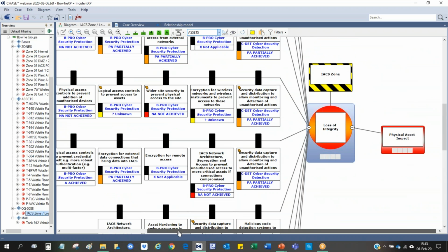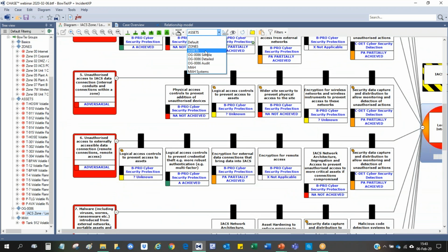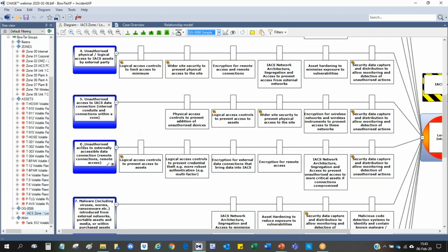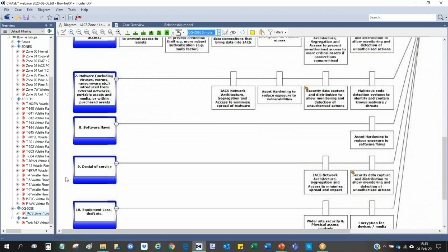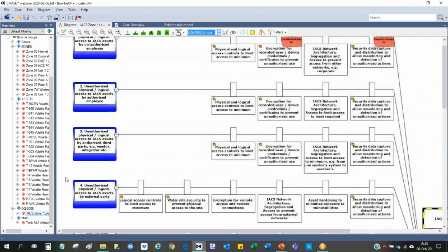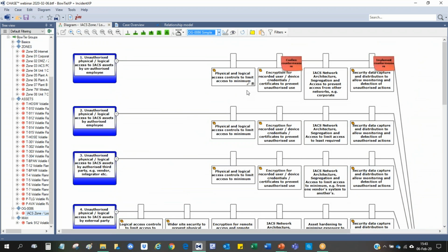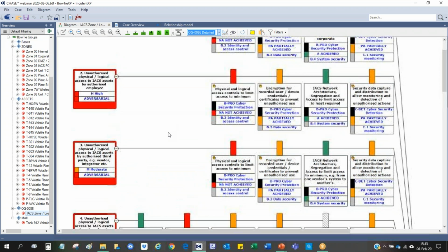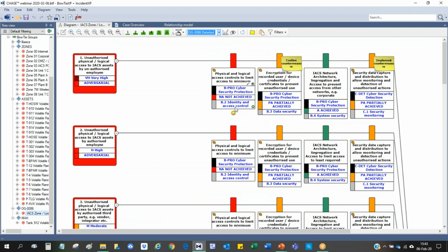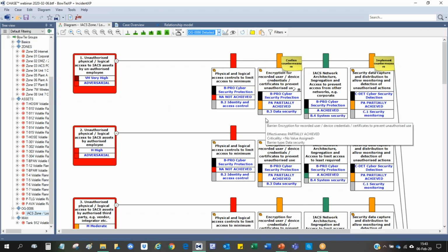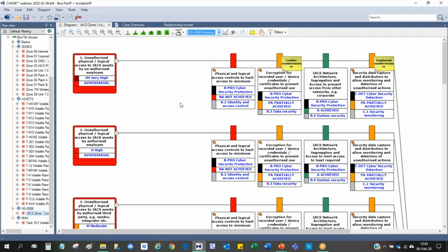Looking at this in more detail for the logical bow tie, here we've got our 11 familiar threats. We've got the expected or anticipated measures in place, and putting some more detail on it: what is the likelihood of the threat? What's the effectiveness of the barrier? That's giving a sense of the robustness of our countermeasures. And here we have some actions to be implemented.